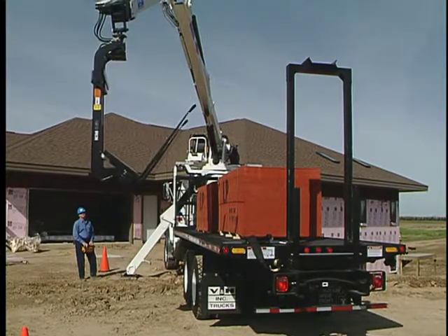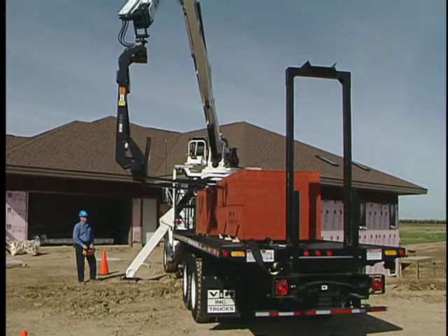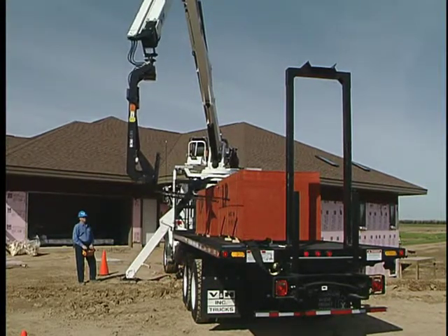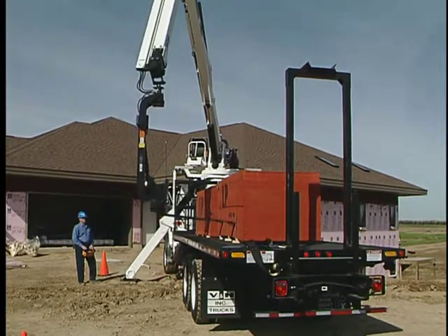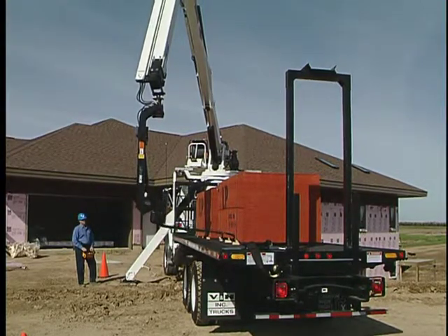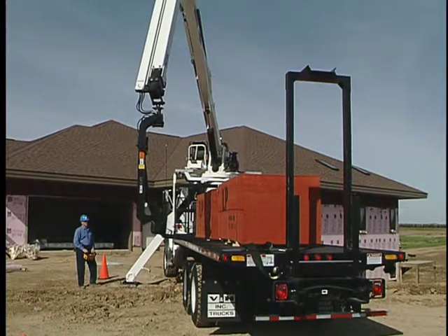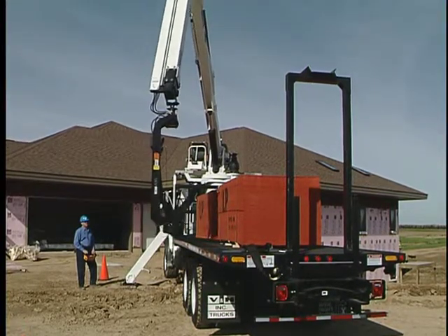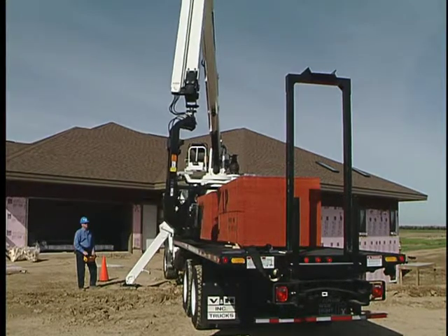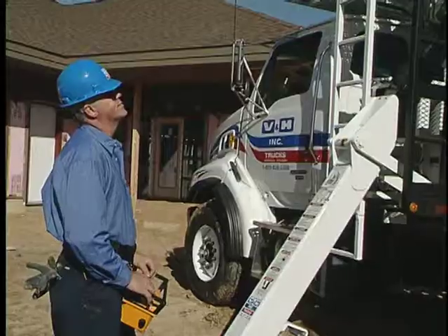Tilt fork down. Raise the inner boom. Lower the outer boom. Rotate boom into position of your load. Rotate fork to get into position for the load. The key is to position boom and fork in such a way that the fork tines naturally slip into the load space. Mark the center of gravity for the load.